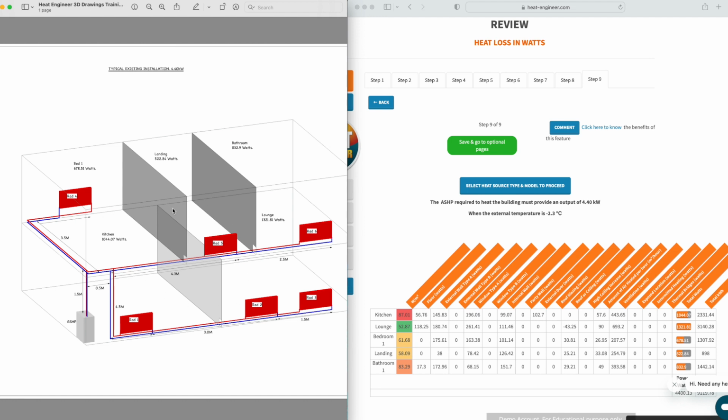That's on an existing circuit, and I bet everybody listening to this now will see that pretty much every single pump is massively oversized. In fact, there's an incredibly frightening statistic that I heard from the guys at IMI Hydronic, and this has been verified many times: between 15 and 20% of the entire world's electrical energy usage is taken up by dead-headed or oversized pumps.